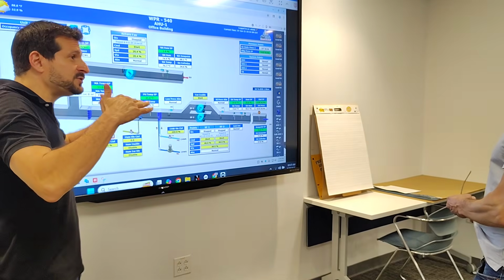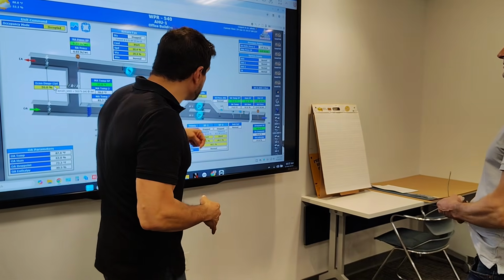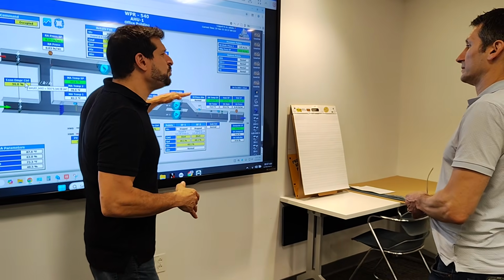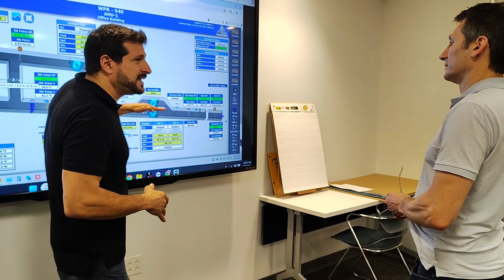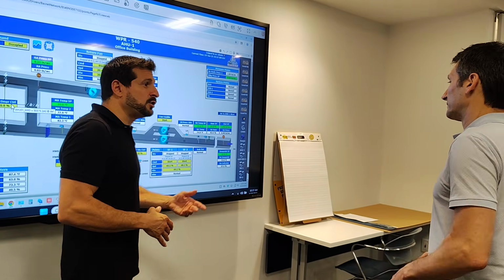He works on all those different things, and then I go in and I go, change the set point to 2, and he changes it to 2, and then I watch this happen, and I want to see this thing come up, get to 2, maybe 2.1, settle back down, and then stay at 2. And if it doesn't do that, then I should go back in and fix it. Right? And then he goes back in and fixes it.